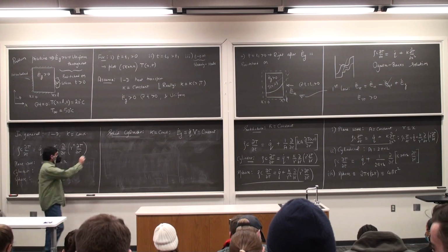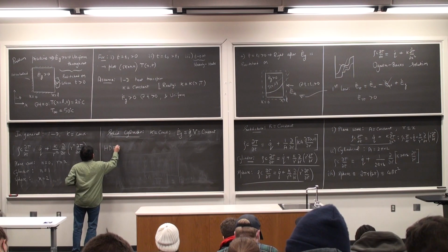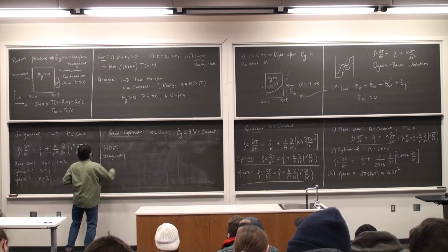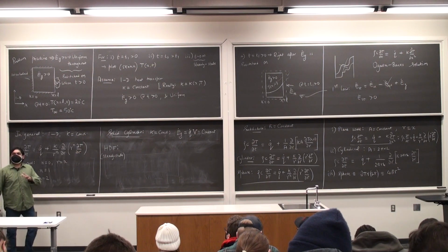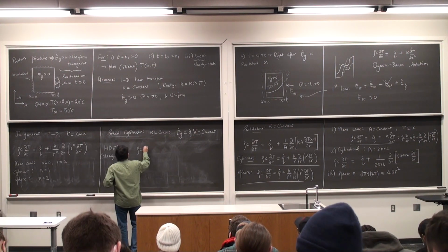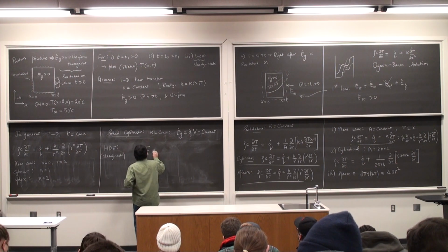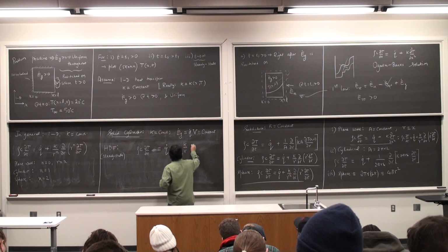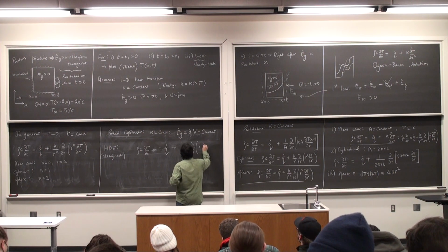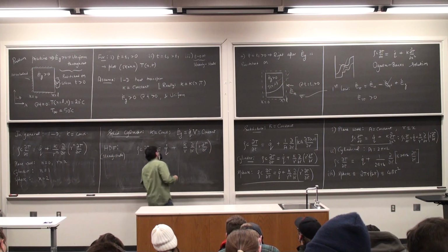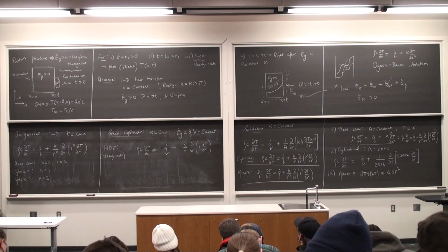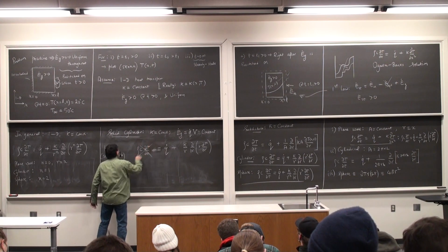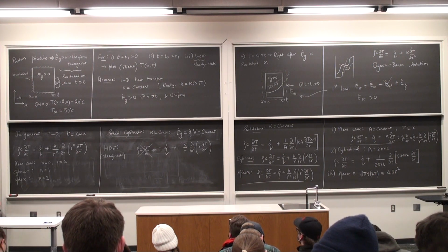Write the heat diffusion equation for steady state. Rho times C dT by dt is gone. This is equal to q dot plus k by r d by dr of r dT by dr. This is just a general equation that we've derived. I'm going to write it down. Steady state, dT by dt is 0. I want to come up with a temperature profile.